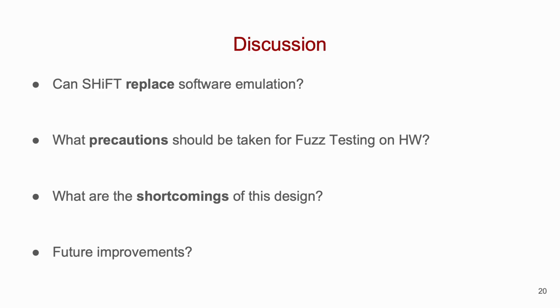Okay, now what are some shortcomings of semi-hosted fuzzing in the style of design presented by SHiFT? Firstly, communication is a bottleneck and introduces large delays in fuzzing speeds. SHiFT uses a high-speed USB-C DC bus, but again, many embedded devices lack such sophisticated communication protocols.